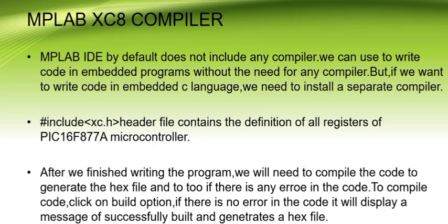MPLAB XC8 Compiler. MPLAB X IDE by default does not include any compiler. We can use it to write assembly programs without the need for any compiler. But if we want to write code in embedded C language, we need to install a separate compiler. The #include xc.h header file contains the definition of all registers of the PIC16F877A microcontroller.